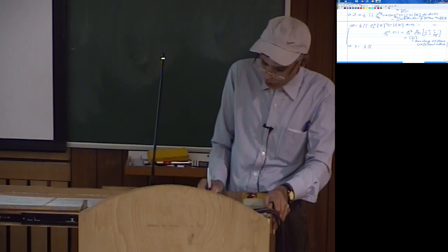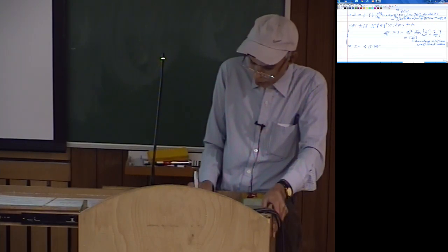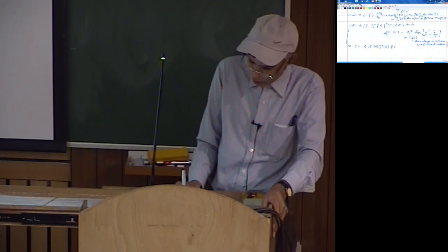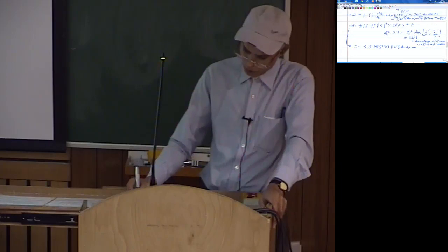So this we call D, and so finally you can see that I can be written as half of the integration over x and y of kappa transpose into this D matrix and into this kappa dx dy, minus the other two terms. This is what you will have.